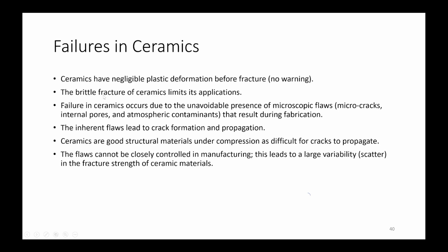ceramics in many applications. Failure in ceramics occurs due to the unavoidable presence of microscopic flaws, such as micro cracks, internal pores, and atmospheric contaminants. All these things can be present inside ceramics during fabrication. When we are fabricating a ceramic, some cracks or pores can form inside it. The inherent flaws lead to crack formation and propagation.